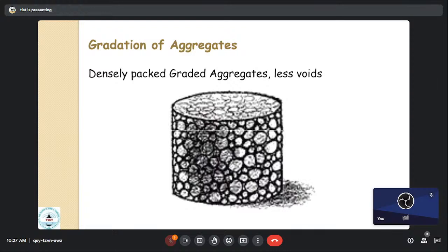So this is the basic phenomenon of any concrete mixture. And this should be in a particular proportion. If your aggregates are more and slurry is less, bonding is poor. And if slurry is more and aggregates are less, again bonding is poor. So I'm also clear. It is as good as your vegetables not being there and masala being too much. And in the other case, vegetables are more and masala is less. Same is the scenario. You are not going to get a very good mark.